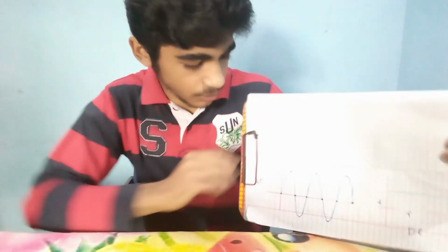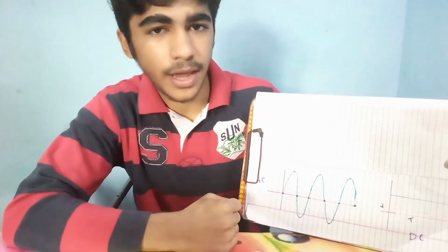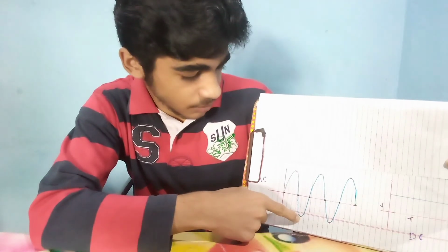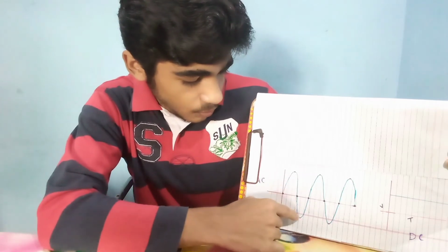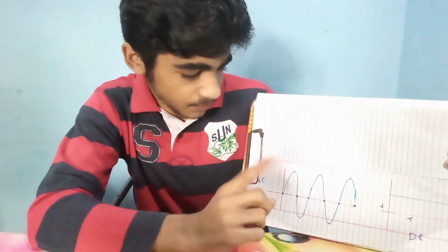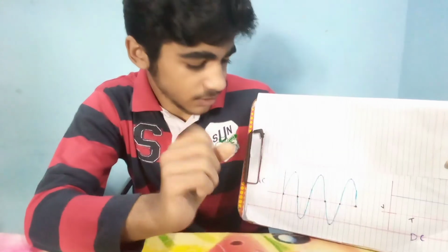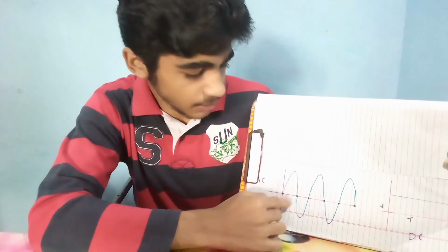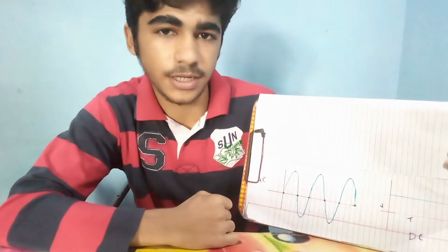The second thing is that you should have a basic understanding of what an alternating current is. An alternating current is in the form of sinusoidal waves and it is called a bidirectional system because it always moves back and forth. This is how it looks, and these points have zero voltage, this is the peak positive voltage and this is the peak negative voltage. From here all the way to here is called one cycle. This portion is called the positive half cycle and this portion is called the negative half cycle.